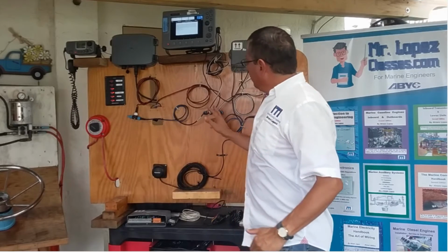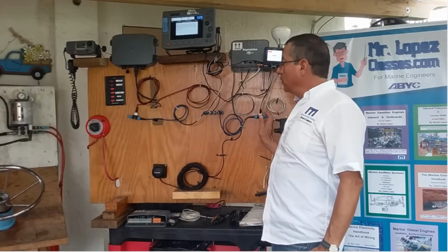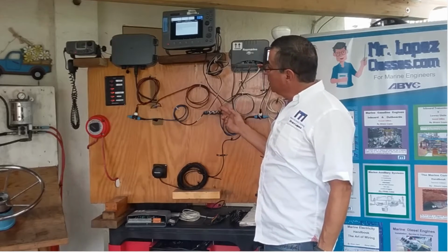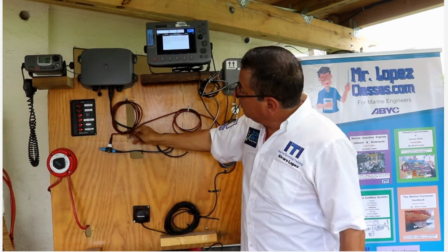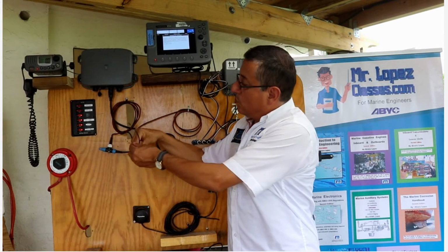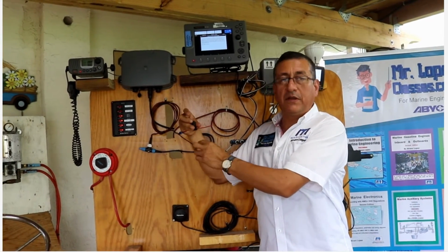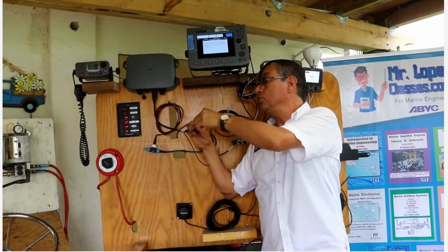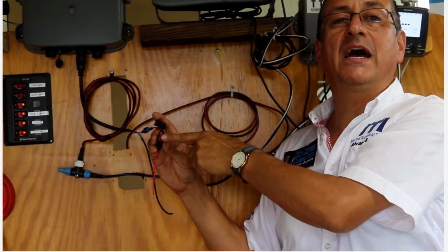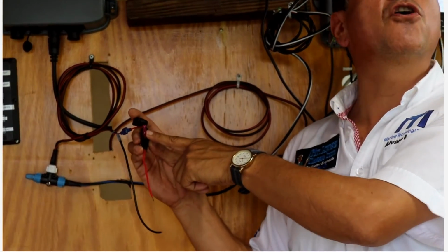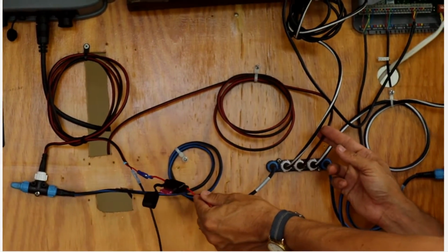Okay, in this particular example, because it's a short backbone, I put one source of power in the middle and the other one at the end. And each source of power should have one negative terminal and one positive terminal. The positive terminal should be protected with a fuse, and the fuse in this particular case is 4 amps, and the other fuse for this one is 4 amps.